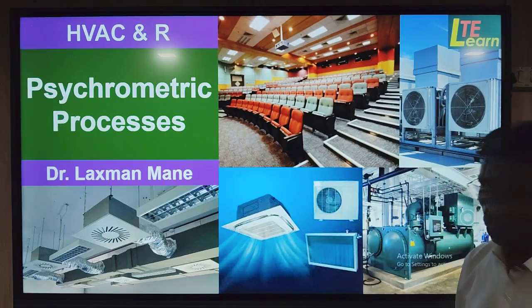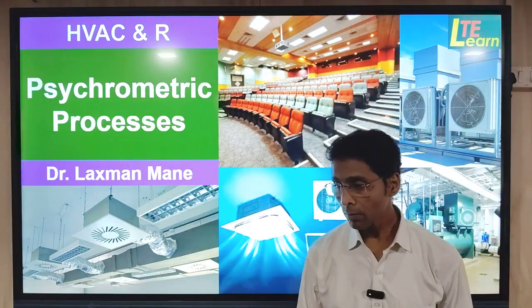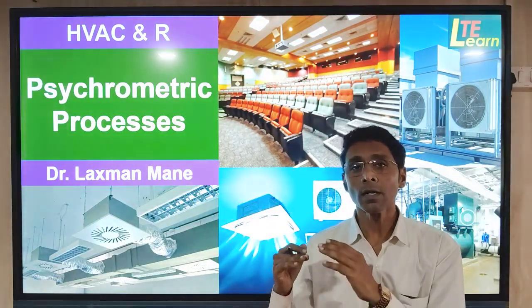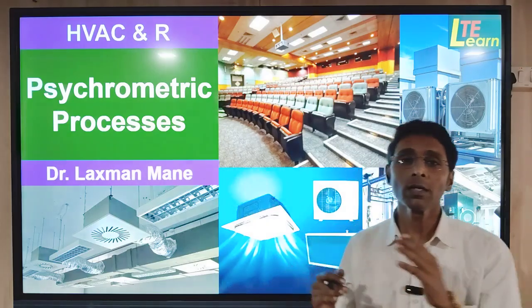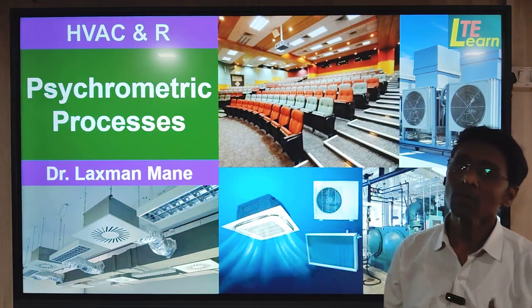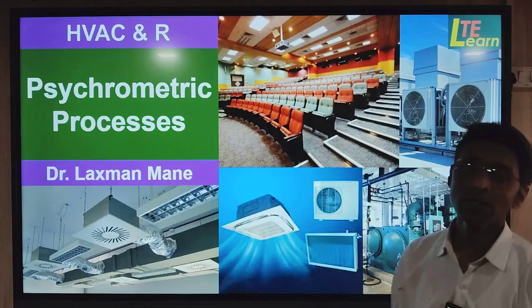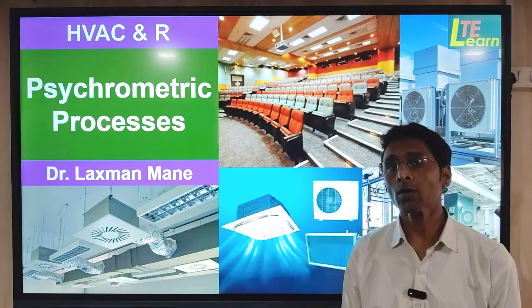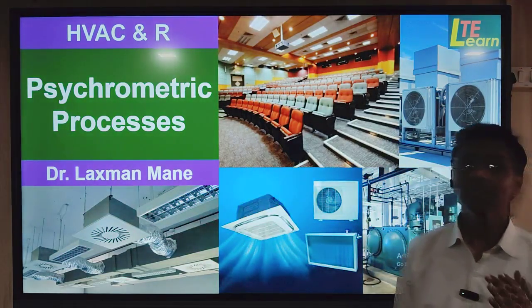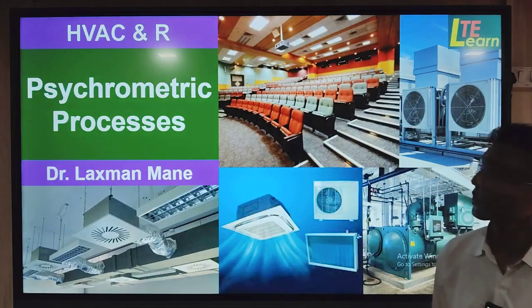Now, what do we mean by a psychrometric process? When the air in a closed space has to be brought to the required climate situation, we have to conduct some processes on the air. That is the treatment of air. The definition of air conditioning, as we have seen, is control of temperature, humidity, purity and velocity in order to bring its quality to the desired level. So to bring that quality, different processes are carried out. These are called psychrometric processes.